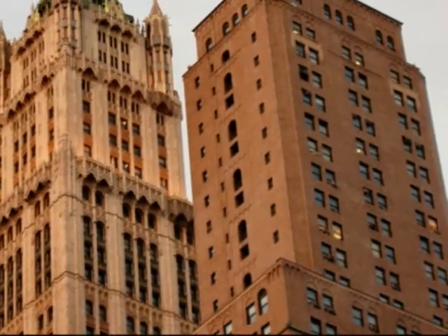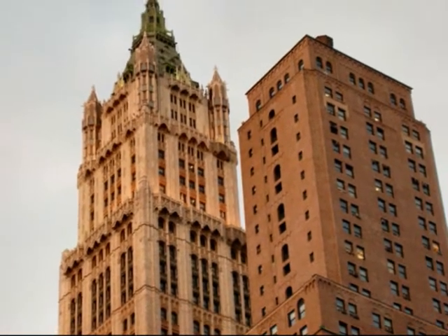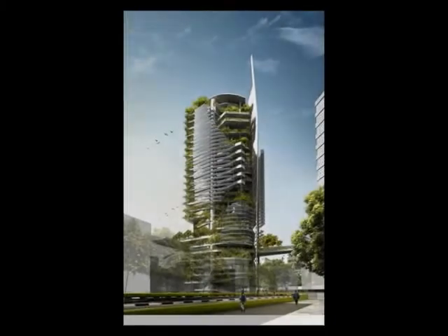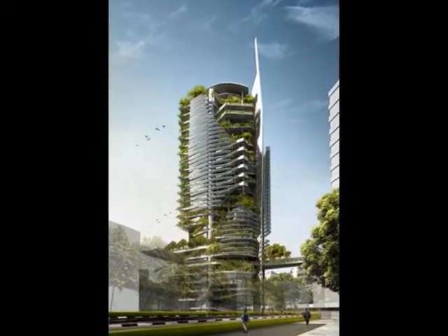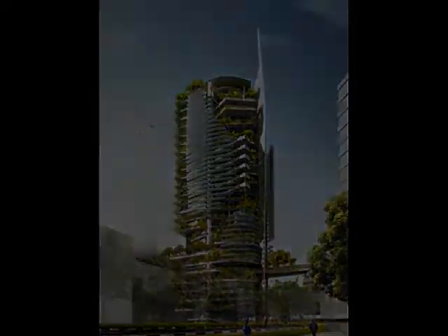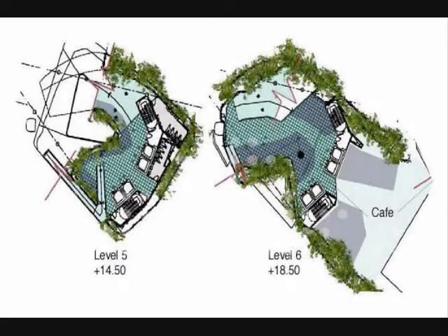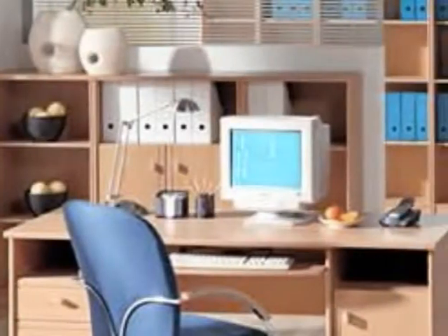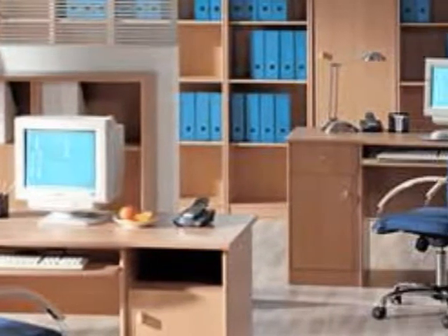Loose fit. Generally, buildings have a lifespan of 100–150 years and change usage over time. The design here is loose fit to facilitate future reuse, for example, removable partitions, removable floors, mechanical jointing of material as against chemical bonding to facilitate future recovery. Flexible design, for example, initially a multi-use building. Its future use may be office or apartments.